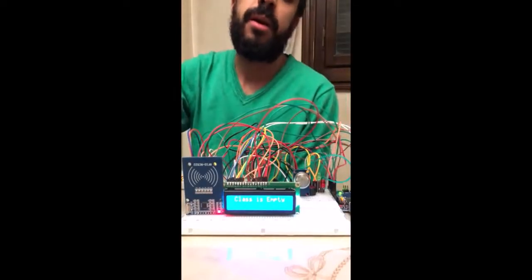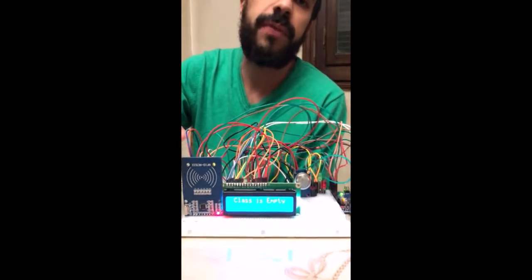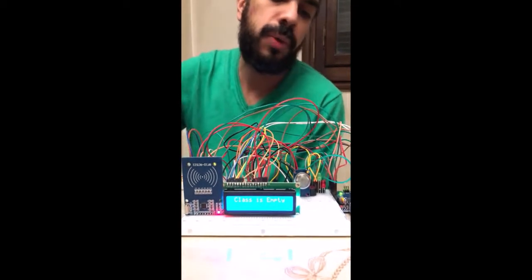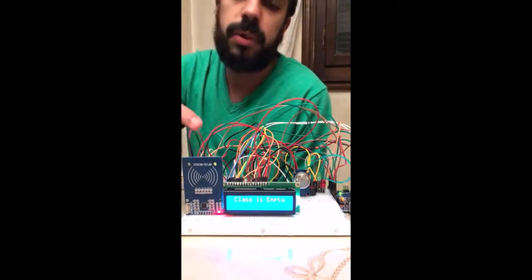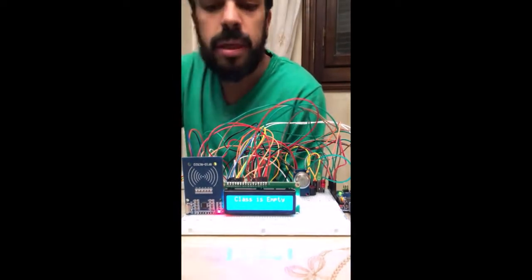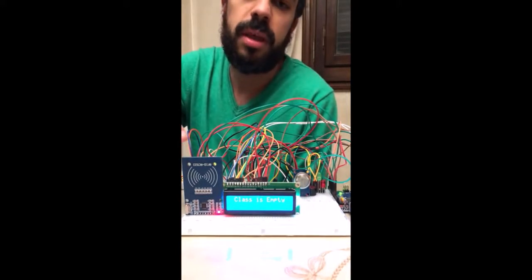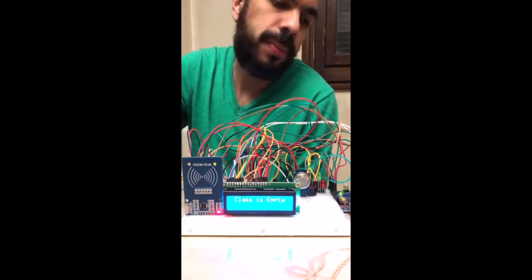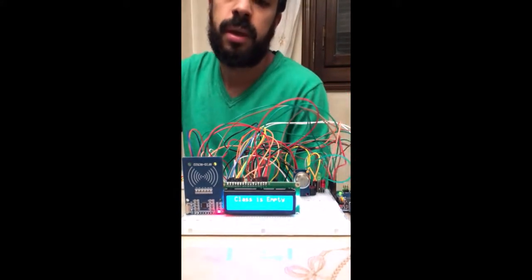Back again. My main responsibility was to connect the RFID with the Arduino board. The RFID has 8 pins, of which only 7 need to be connected, and 1 pin is disconnected or not connected to anything. The only difference with this component is that it has to be connected to the positive 3.3 volts of the Arduino board, not the 5 volts.